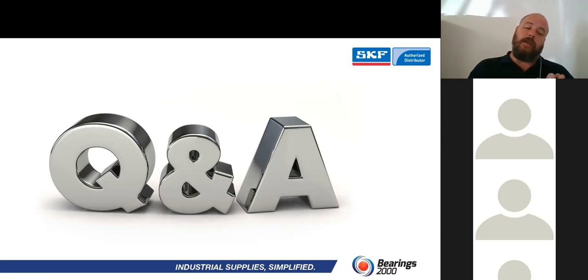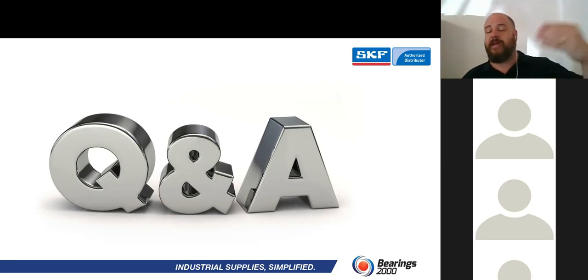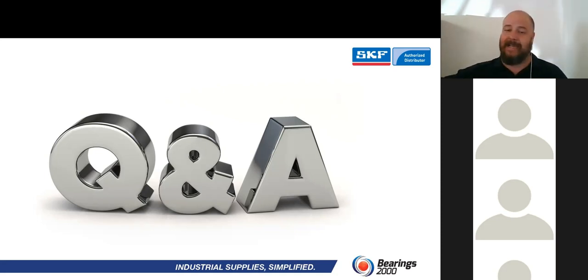In 90% of them, I would say, they are completely interchangeable with the spherical. So where you had a 22216 EKC3, you will replace it with a C2216 KC3. So yes, Craig, you and I will have a nice chat about that, and I'll share some successes on that, and we'll see where we go from there.